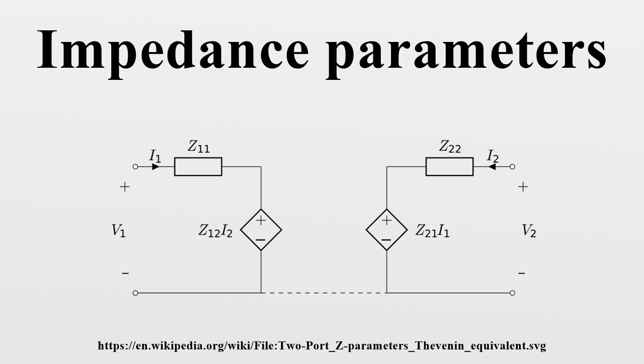Two-port. In the special case of a two-port network, with the same characteristic impedance at each port, the above expressions reduce to the following, where the two-port S parameters may be obtained from the equivalent two-port Z parameters by means of the following expressions, where the above expressions will generally use complex numbers for Z_n. Note that the value of the denominator can become 0 for specific values of Z, so the division by it in the calculations may lead to a division by 0.